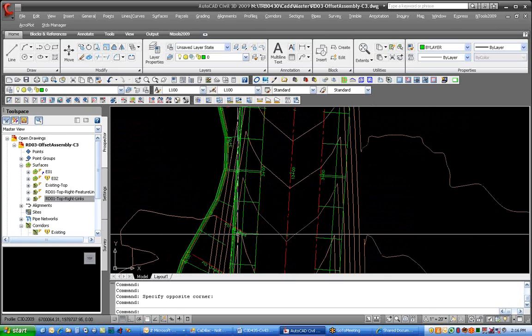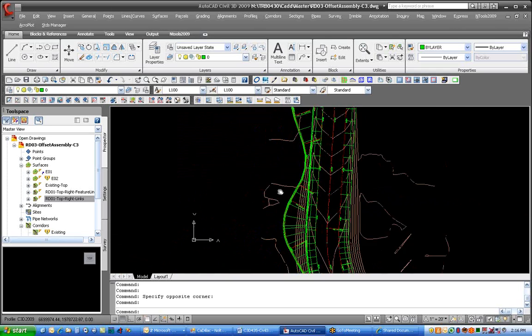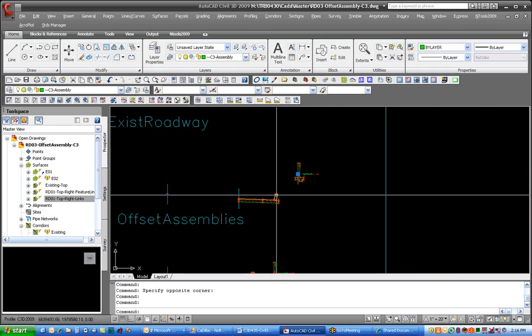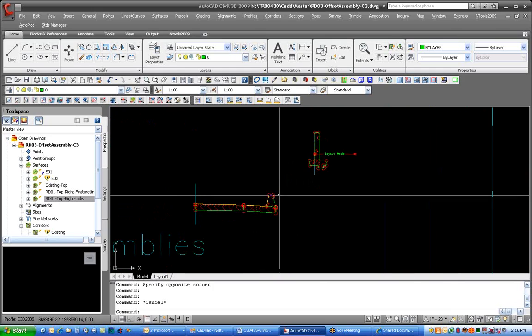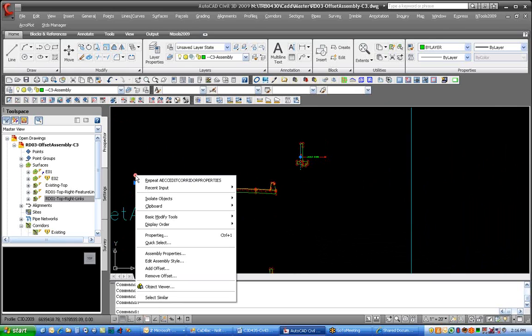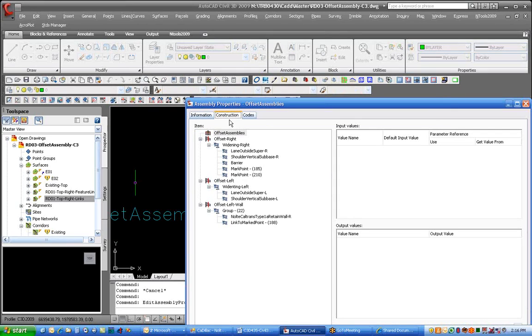At the end of today's little session, I've come up with a fix to this also, and it has to do with the order in which I've assigned the offsets and then doing that link. I've got the link going from this one to this one because you have to do it in such an order that the mark point is placed first and the link is placed second. And you can see that by going into the assembly properties and looking at construction. It processes it in this direction here. So you can see as we come through,